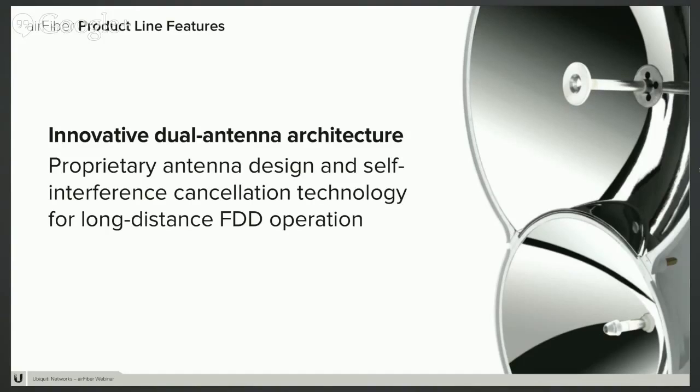Finally, this antenna supports something which is a little unusual: slant polarization. We're a two-chain MIMO radio. However, rather than doing vertical and horizontal polarization, which is pretty typical out there, we're using slant polarization. The reason for that is that it helps us better isolate reflected signals. It takes advantage of the fact that a lot of the reflective surfaces that you'll see out there are either horizontal, like the ground, or vertical, like a building. When you put this all together, what it adds up to is excellent full duplex performance.